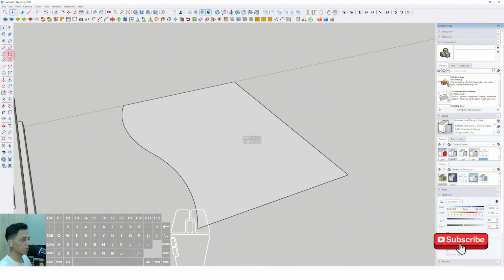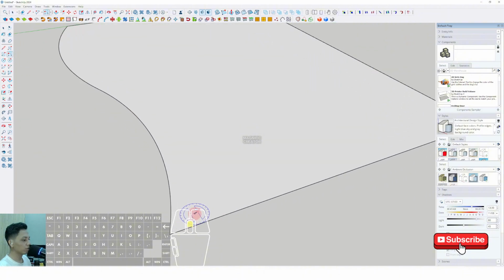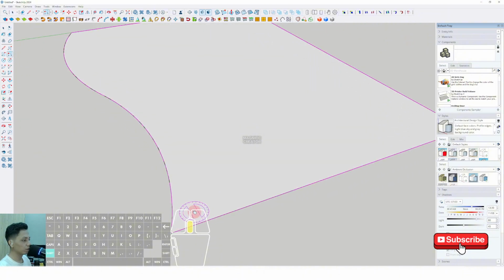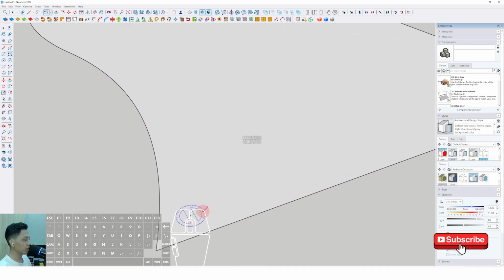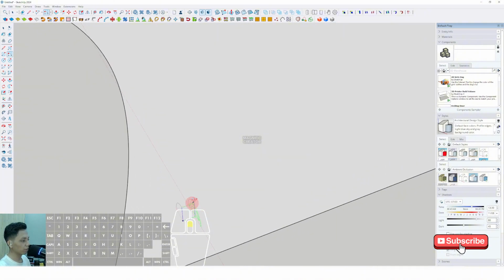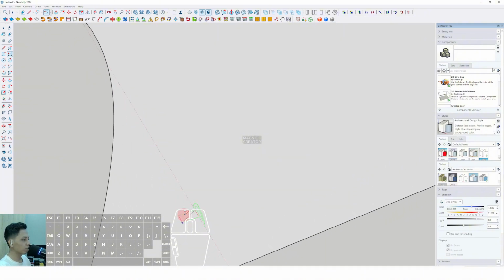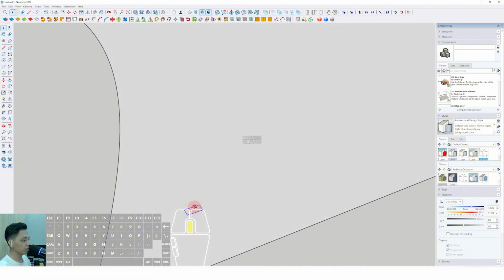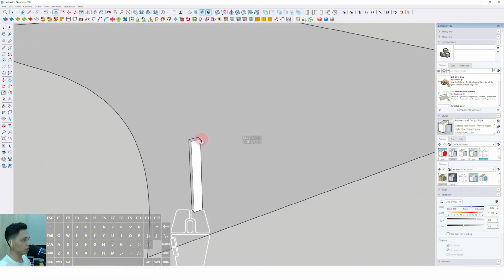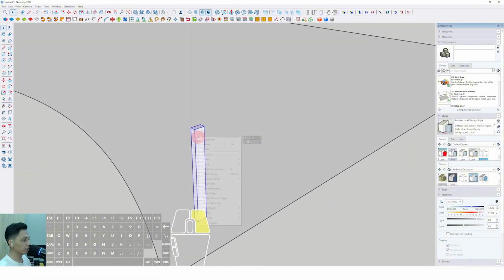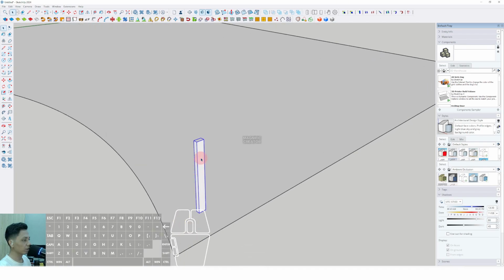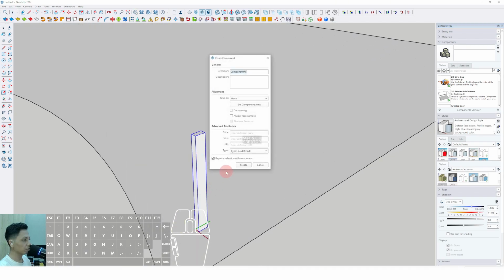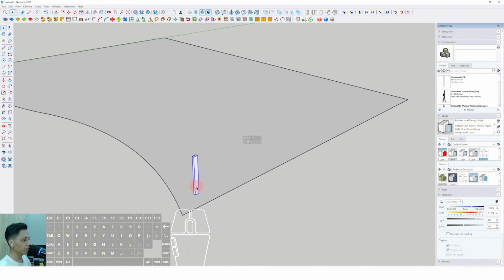Okay, then we can select rotate rectangle and click at any position. Then we can type 200 millimeter, enter, and we can set the depth of this frame around 100 millimeter. Then we can triple click the surface and push it up just a little bit. Then we can triple click, make group, and then right click and make component and create.